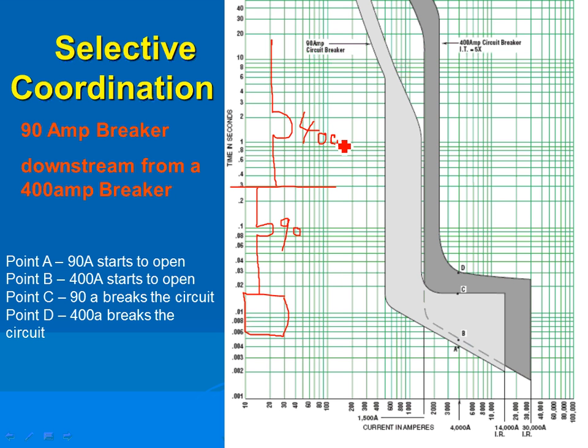So we send one of you, my friends, to go work on this machine, and whatever happened, you shorted. Ground fault, since 85% of faults are ground faults. Or you decided to put phase A and phase B together. Could that happen? Not a whole lot, but okay, which one do you think is going to trip? It should be the 90. Here are the curves, guys. These are fancy curves for nothing. All you're looking for is, are they touching? Wherever they touch each other, there's miscoordination. So look at them from top to bottom. Are they touching? The only place where they're touching is right here, overlapping, right?